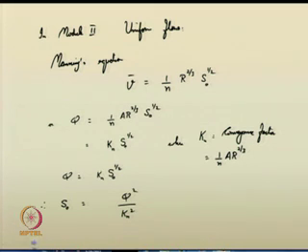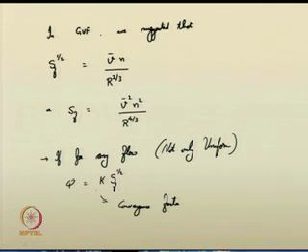Similarly, in other types of flow, you can suggest the discharge Q is equal to some conveyance factor K into the square root of the friction slope S f. Like that, one can easily now derive your S f, or your energy slope, friction slope.